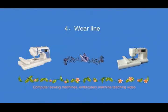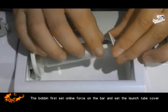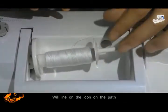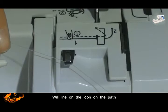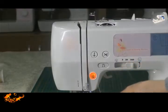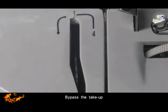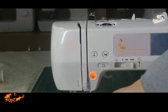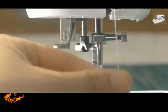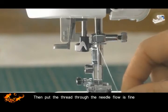4. Threading. The thread is first set on the thread rod and the thread cylinder cover is set. Pass the thread along the path on the icon, through the wire hook, and then through the wire cover. Thread according to the path of the printed icons from 1 to 5. Bypass the take up. Then put the thread through the needle eye, and that is fine.